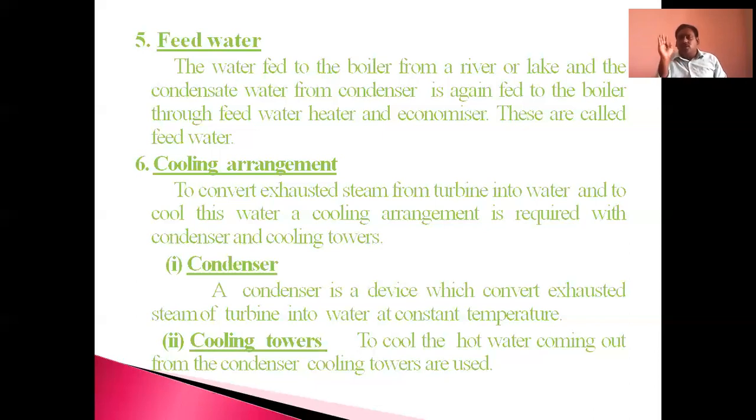And in this powerhouse, along with the alternator, an exciter is required to excite the alternator for the production of a stationary magnetic field. And most importantly, a transformer is required to step up the generating voltage to a higher voltage to reduce transmission losses. We already discussed this in the power system architecture introduction. After the stepped up voltage, power can be delivered to the transmission system with the help of protective devices like isolators and circuit breakers. And finally, through bus bars, we can deliver to the transmission system. This is the importance of the powerhouse.